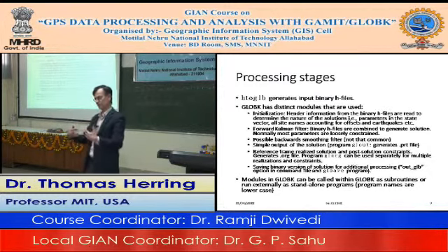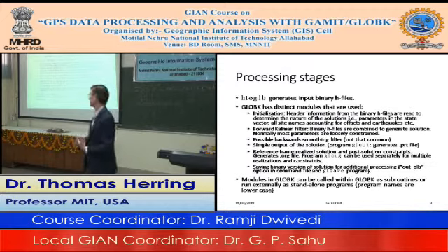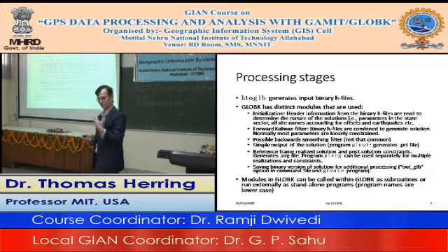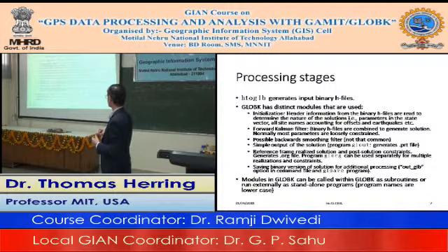That solution you would save as a binary file, which then later on you just treat as the 500 station file. Or if you are doing campaign data, you might have 2 weeks worth of data. You combine it all together and save the results. So you have one file that contains all of the survey results in that one single file. And as I said, the modules in GLOBK can be called within GLOBK itself as subroutines, or they can be run externally as standalone programs.